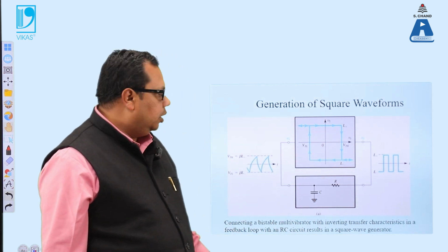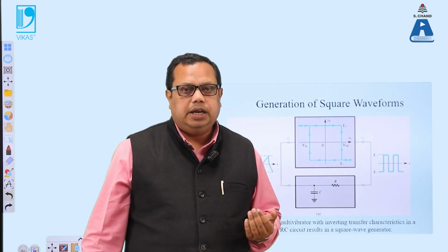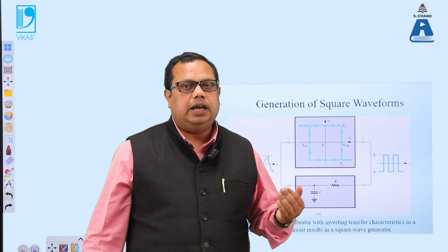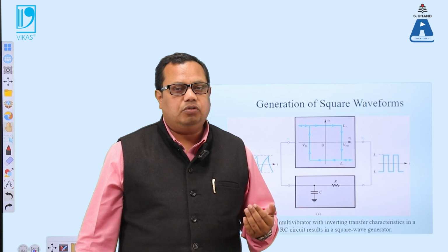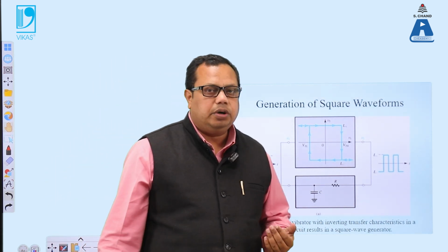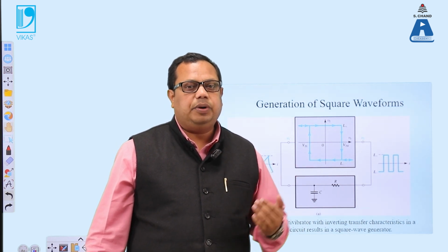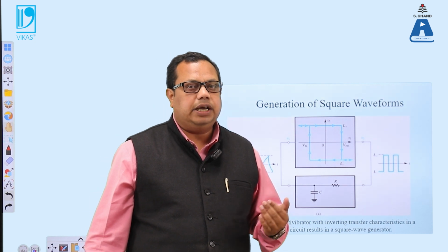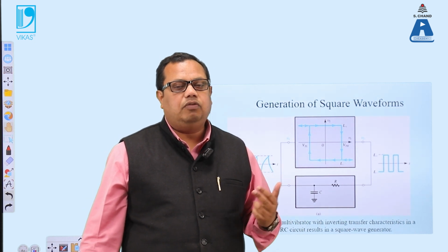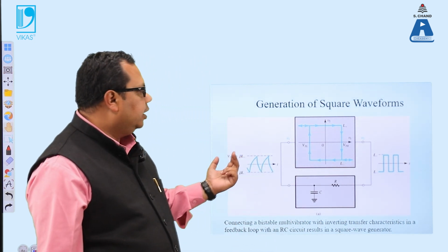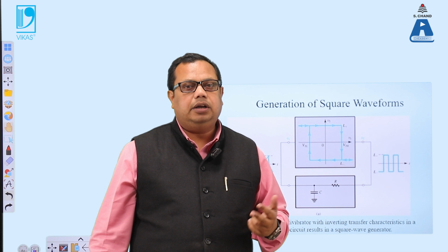The output is required in the digital form. So we again analyze how the operational amplifier we studied as a bistable circuit, then as a circuit that gives a defined output by connecting a bridge in the output. After connecting the bridge in the output, we can see how it works as a multivibrator circuit, and when the operational amplifier in bistable mode, used as a multivibrator, is connected to the RC circuit, then we can give the input in analog form and get the output in digital form. We can give the sine wave in the input and we get the square wave in the output.